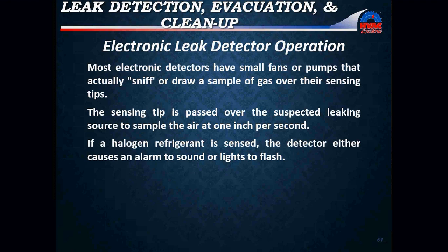And if the environment is contaminated with many refrigerant leaks, an ambient compensation device will compensate for the contaminated environment. Ambient compensation automatically calibrates the leak detector sensitivity to the ambient temperature surrounding the tip, and ambient compensation makes the detector less sensitive, allowing the source of the leak to be pinpointed a lot better than having other issues or causing nuisance or false alarms.